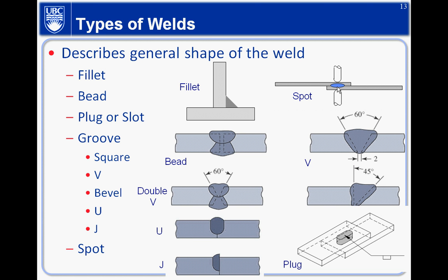Basically, they use electrodes on two sides of the metal, causing current to pass through the metal, joining the two pieces of metal together. They might be sheet metal or something else, right? If you're moving along the metal instead of a spot, it's going to be a so-called seam weld, right? It's kind of like sealing the gap together.